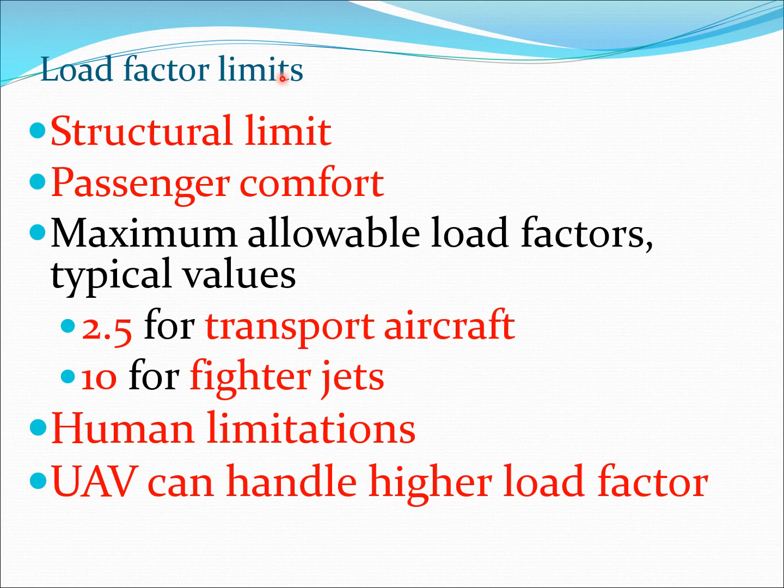There are certain limits in terms of load factor. You cannot use any random large number. There are structural limits, so if the load factor is beyond a certain limit, the structure will fail. Passengers also feel very uncomfortable at load factors of more than 3 or 4. They start feeling perturbed. There are also certain maximum allowable load factors often used for aircraft. For example, for transport aircraft this may be 2.5, which is the maximum they can take, and for fighter jets it could be up to 10. Do remember that some fighter jets go beyond this also.